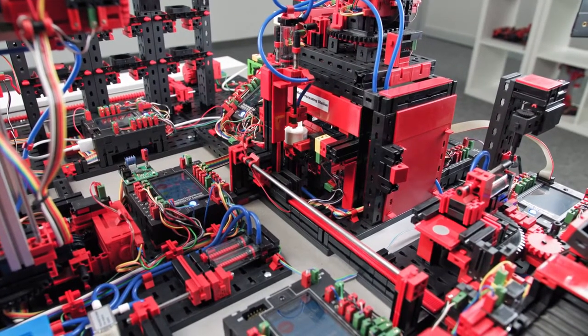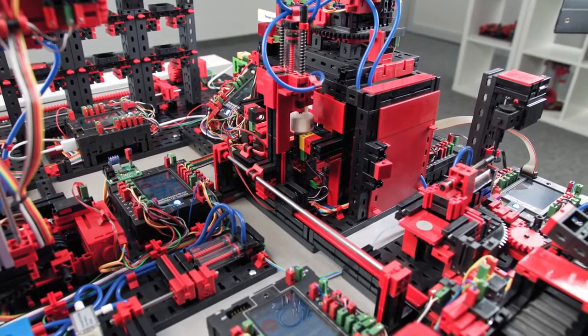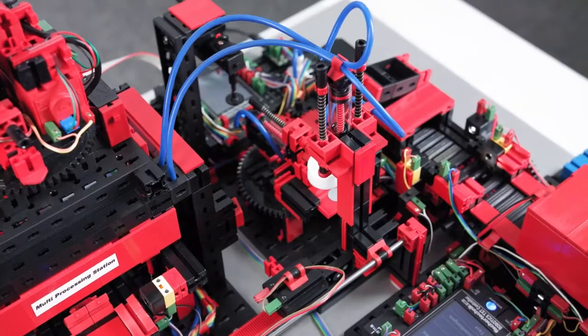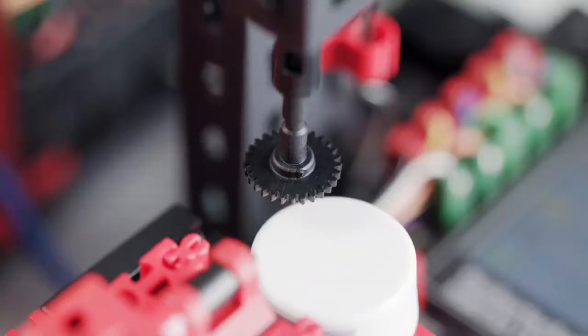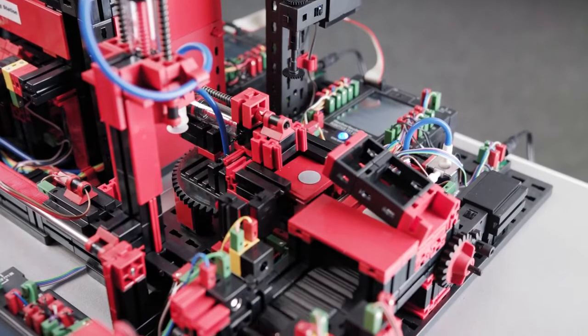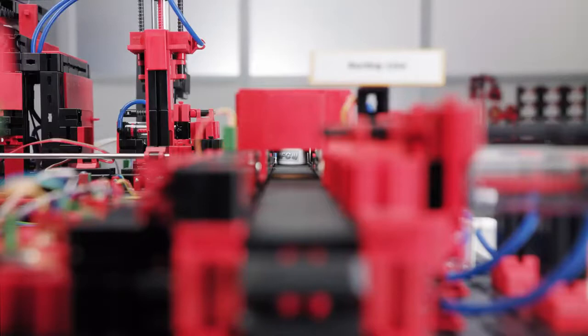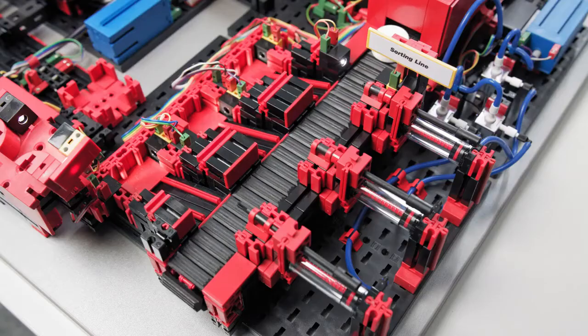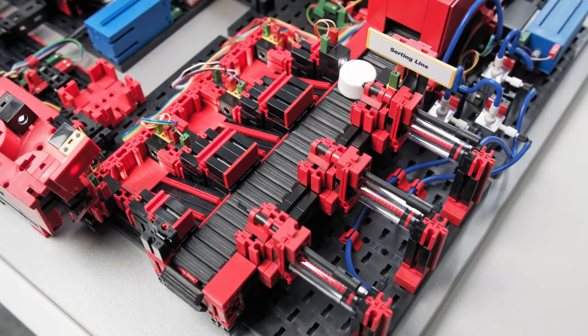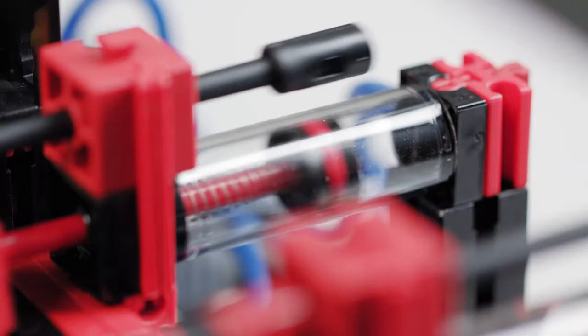The suction gripper passes the material on from one step to the next. The material is transferred to the sorting system once production is complete. The sorting system receives the allocation command as soon as the color sorter detects the proper color. The material is sorted using pneumatic cylinders.